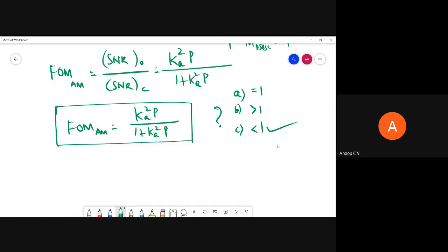That is because, for the sake of simplicity of the transmitter and receiver, we are transmitting redundant power which does not carry any information. This is carrier power. Even though it can help reduce the complexity of transmitter and receiver, it's actually an overburden, an additional power which does not carry any information. So when it comes to noise performance, it affects it adversely.